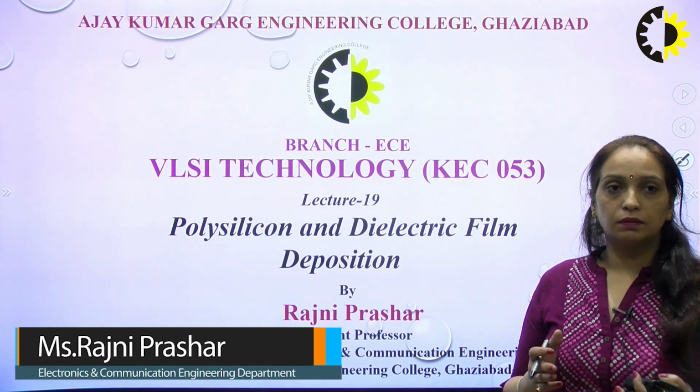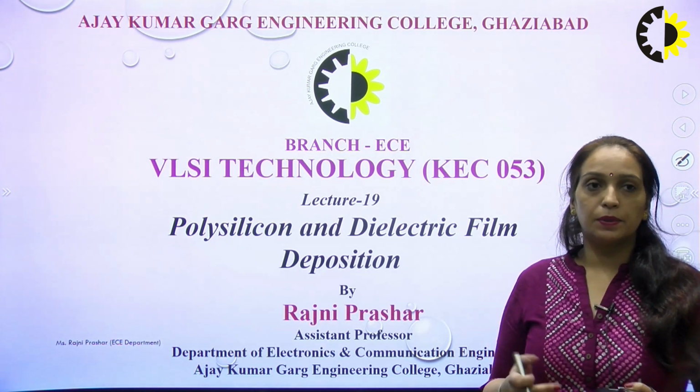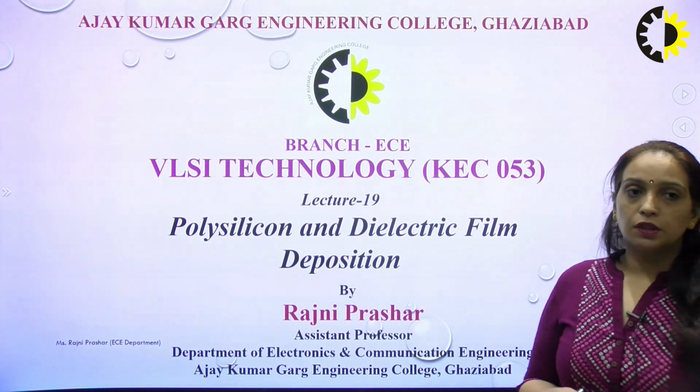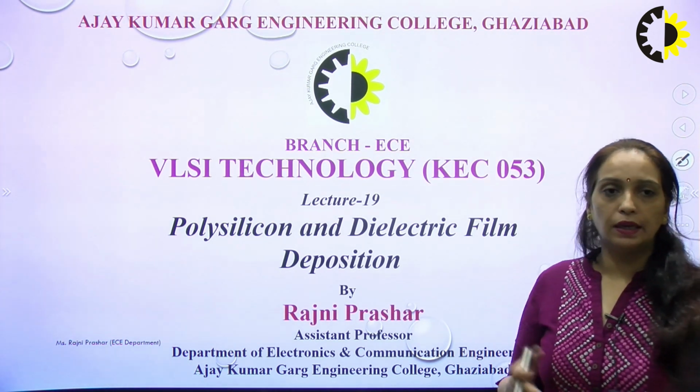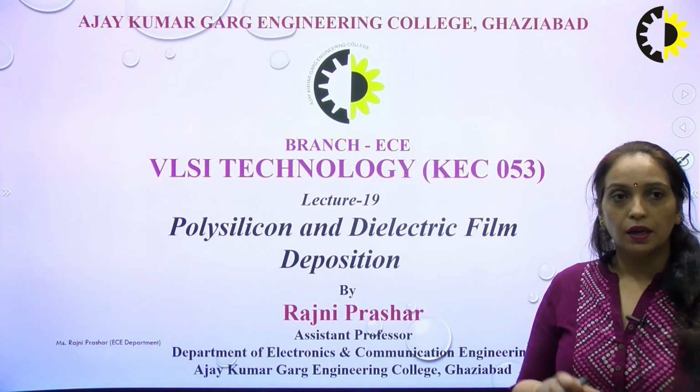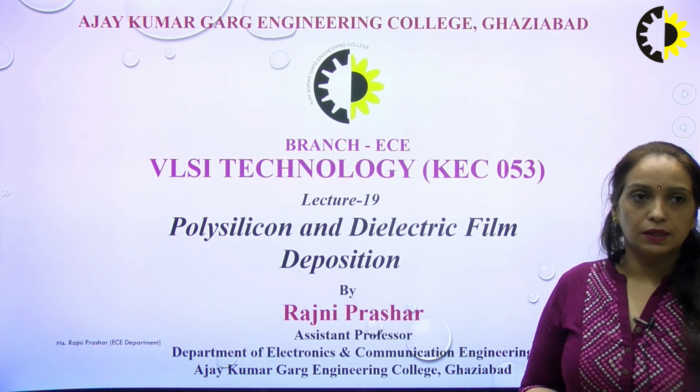In the last lecture we started the deposition process. After the photolithography and the etching process, the next step is to deposit some material which can work as a gate or any other protecting layer for the further steps, right? The very first material which we are going to deposit is polysilicon.